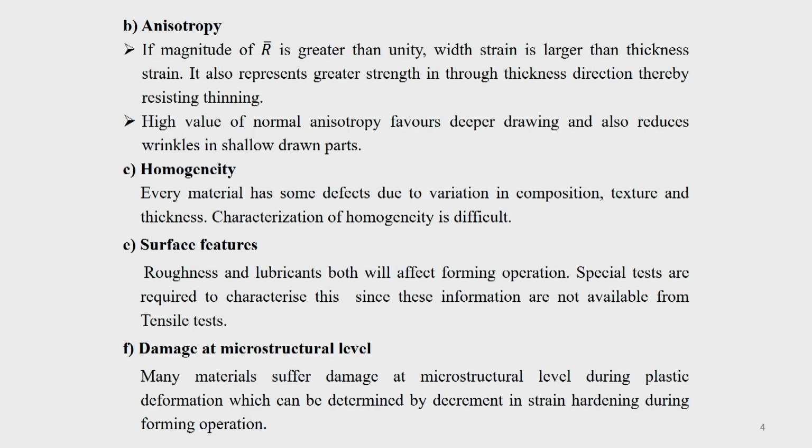So, local necking and then fracture, that part will be reduced. You can have a higher amount of strain for that. High value of normal anisotropy favors deeper drawing operation. So, you can have a very deep cup and other things made, and also higher normal anisotropy will reduce the wrinkles which can form in shallow parts. So, these are some of the advantages.